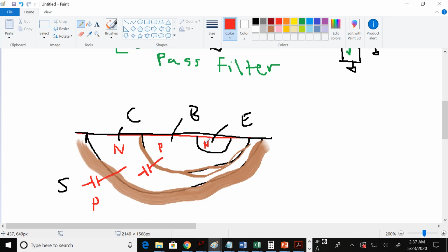Just like with the transistors we used when we needed something that behaved like a large resistance, it wasn't really a resistor, but it behaved like one. In this case, even though this junction is conducting and there's no depletion region, it still has capacitive behavior. When you change the voltage on the base or the emitter, electrons have to travel, and it takes time for them to travel, so it actually looks like there's a capacitor here.